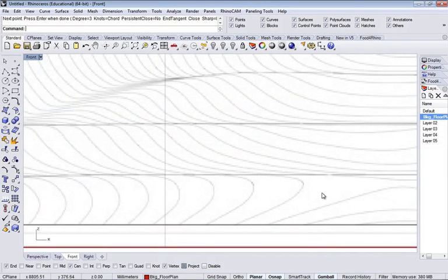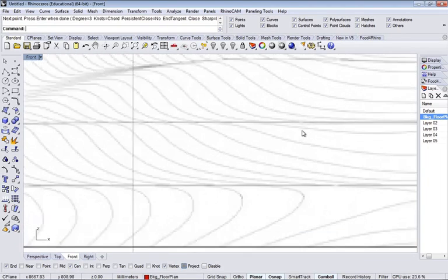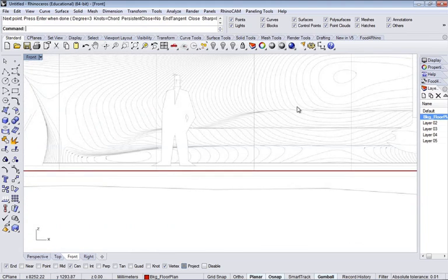So we can move that curve up to that section, and we have the starting point for that. We can do that with each of those steps, and then we can start to add additional curves in between to understand its shape, and then we can loft between those. So it's a very simple set of giving yourself some curves to guide what you're doing, and then building up this piece in a sequence.